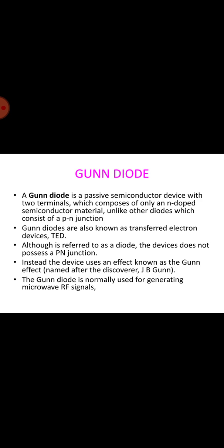Several single throw switches can be combined to form a variety of multiple pole and multiple throw configurations. This diagram shows the series and shunt circuits for a single pole double throw switch, and such a switch requires at least two switching elements. In operation, one diode is forward biased in the low impedance state while the other diode is reverse biased in the high impedance state. The input signal is switched from one output to the other by reversing the diode bias states. The quarter wavelengths of the shunt circuit limit the bandwidth of this configuration. This diagram shows the single pole double throw PIN diode switch.